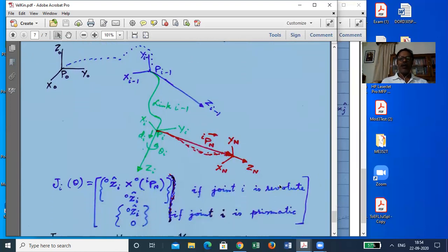So if it is a revolute joint, then you see omega cross this position vector, that is, in this frame whatever is the position of this, and that you know because position analysis you have already done, and this direction also you know because position analysis has been done. Direction is dependent on the configuration, on the position.